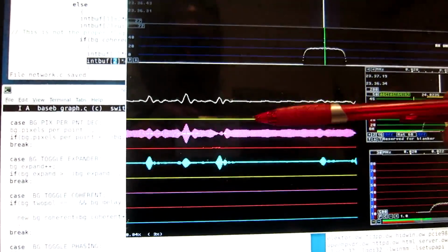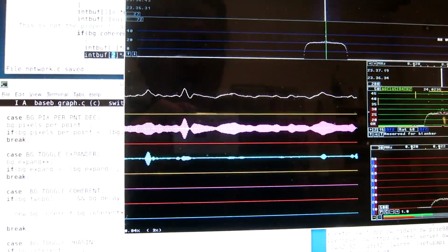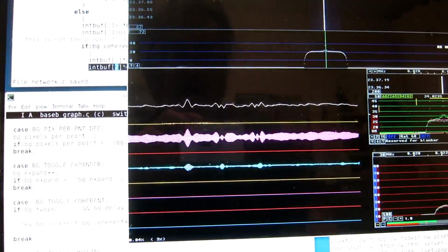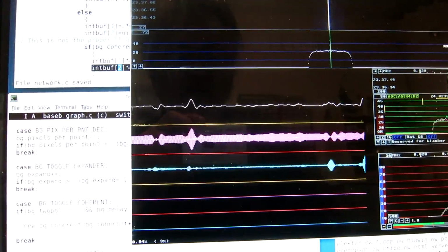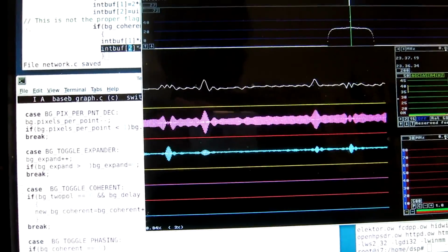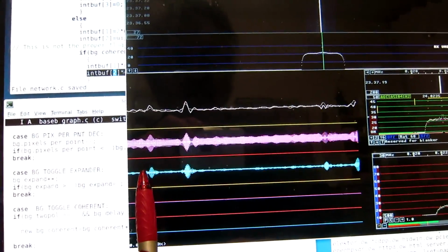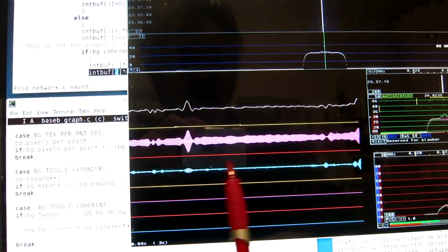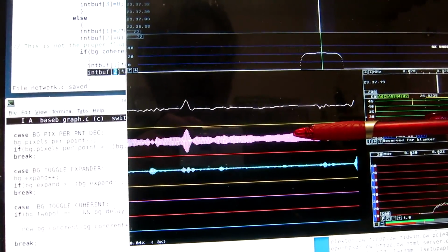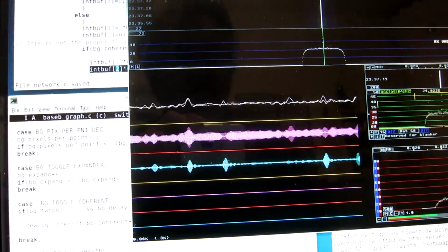They come as I and Q, here and here, but this is loudspeaker output, the baseband. So it is real valued, so one of them is 0 and the other has the signal. The interesting thing here is that in the orthogonal part that is sent from the other computer, we have the interference only, while in the first channel we have the AM station plus the interference.